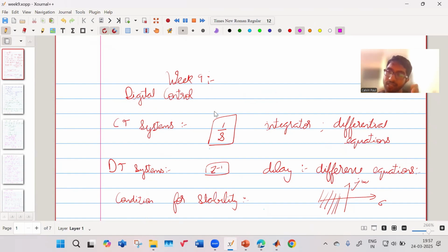There should be a minimum number of samples required, which is found by the observability index. If you get that certain minimum number of samples, then you can do arbitrary pole placement. In that case, you don't need an observer, you don't need to estimate all the states.